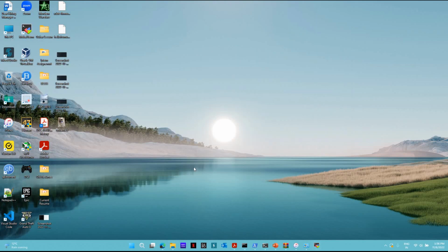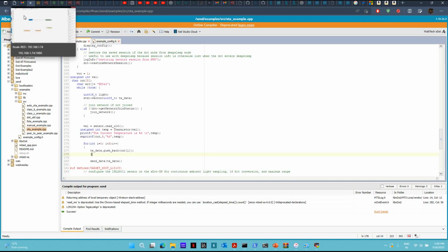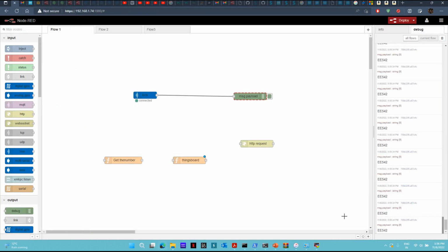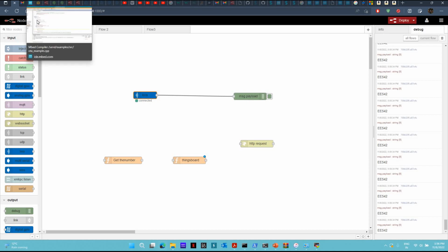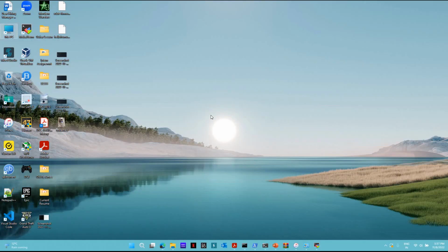Okay, so this has been completed. What's going to happen is this sensor data should be available over here as this LoRa block receives the temperature data. Also, since we have included a printf, it should be available through the debug port. So let's do that. I'm going to press the reset button and let's check it out.